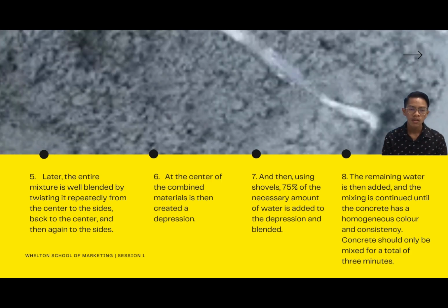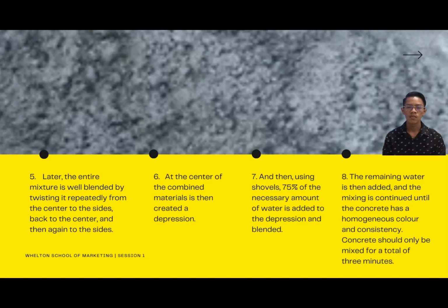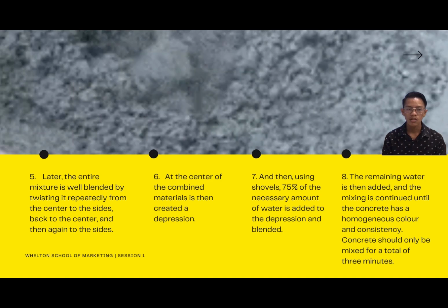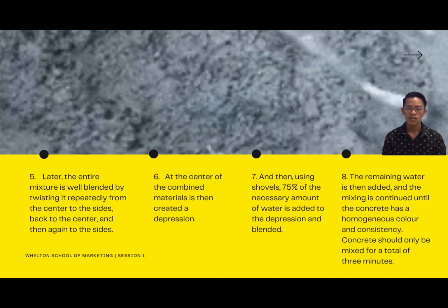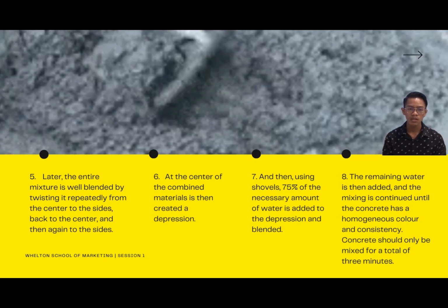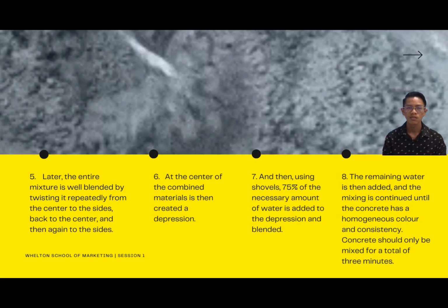Number 8. The remaining water is then added, and the mixing is continued until the concrete has a homogeneous color and consistency. Concrete should only be mixed for a total of 3 minutes.